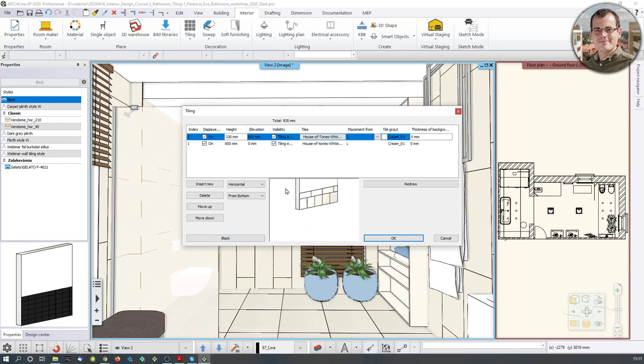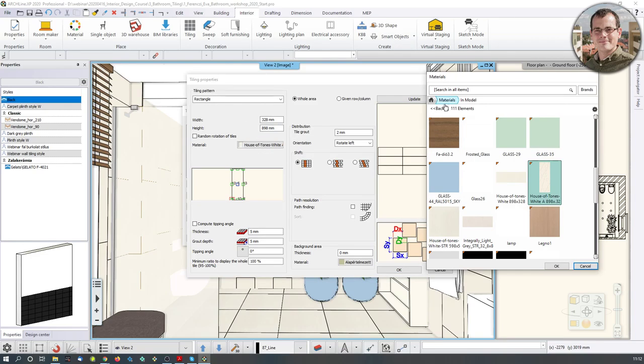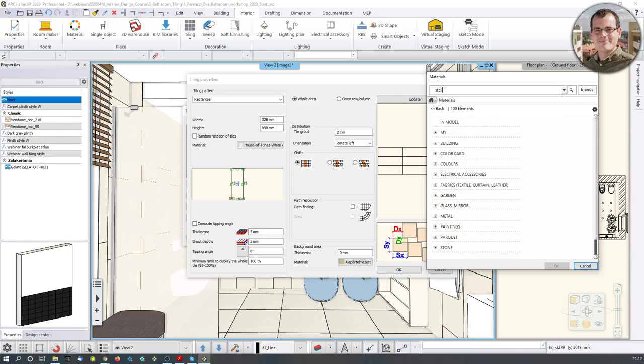But there should be sort of a boundary of another very thin golden line over there. So I do that by inserting new and again resizing it. It's going to be 23 millimeters thick altogether. You see that the software tries its best to make it full with cut tiles, but that's not what we want. We will go to the tile manager and we are going to browse for another tile, which is called steel gold. Oh, sorry, steel goes with 2 E's, not 2 L's. Steel gold. That's the one.